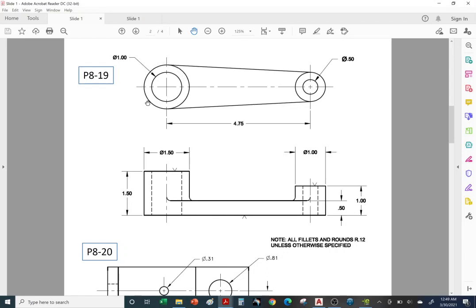The large circle is a solid. It's the shaft, right? Same thing with this one. So the large circles are shafts, so you do not dimension the circles, you dimension the rectangular view, right? So this large circle here is 1 inch in diameter, but you have to put the dimension here because this large circle is a solid. Same thing with this circle. It represents a shaft, a solid. So here is its diameter of 150.